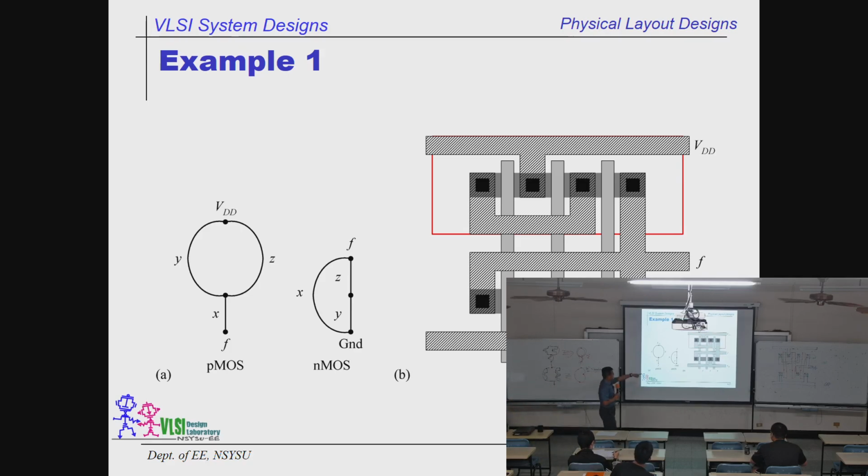So this is one close to what I just did over here. See that? If you follow the Euler path, this is one, the same over here, and this is one over here. We have 2 in parallel, just like these 2 over here. Then this is the last one on the top. So this is a better, more compact layout than a design where you don't follow the Euler path.